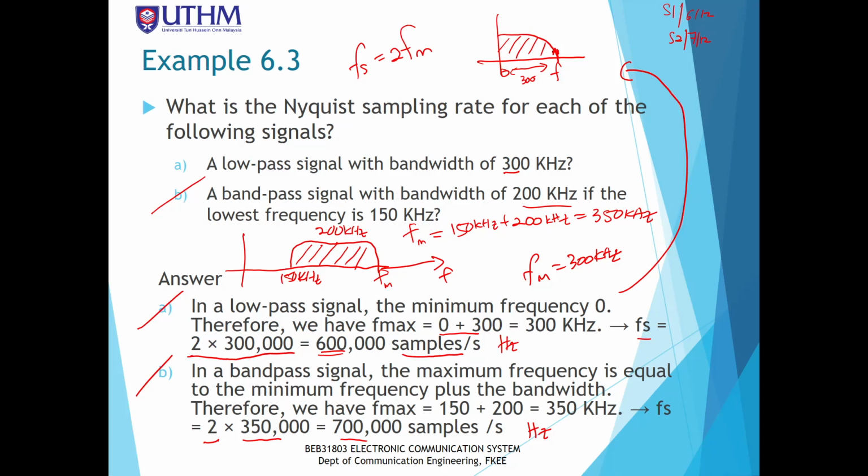Okay, so this example is straightforward regarding the sampling rate. Sampling rate, normally we ask in the exam, calculate the sampling rate, quantization and so on. So this is the beginning, which is the sampling rate. Sampling rate minimum is 2 times the highest input frequency. Okay, so you can sample more than 2 FM. It cannot be less than that. If you sample less than 2 FM, there's going to be aliasing effect.